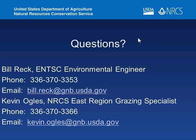Yeah, let's go over a few questions. We got a question that came in about float valve pressure and why is there a minimum pressure to open, and it has to do with the mechanism on those float valves. You want there to be a spring or something that's going to close that valve and to shut it off. And to overcome that pressure, you're going to have some minimum float pressure. So that's why you have a minimum pressure to open a lot of float valves.